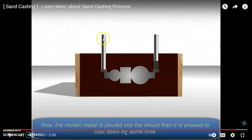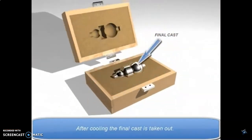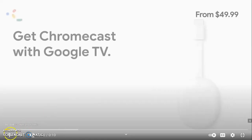Okay, so here you can see I have created the two holes. Okay, this is my required shape, and this is the material added to this hollow shape. Actually this was the empty shape. As you can see, when we fill the material, when we fill the liquid, okay, this was the molten metal, it was filled in this shape, and exactly the excess material goes to the upward direction. After that what we'll do, we will remove this cope and drag, and ultimately we will get the final product.